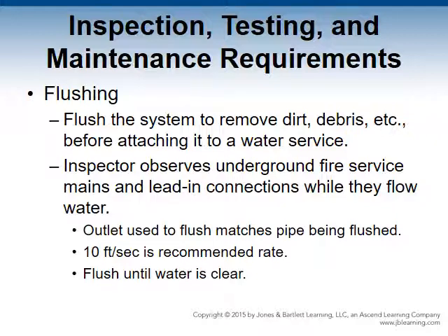Flushing. Before connecting the standpipe system to any water service, the supply piping must be flushed. This is going to remove dirt, stones, and other debris that could clog or damage the system or compromise its performance in any way. The inspector observes the underground fire service mains and leads-in while they flow water. It is a simple process. It is best if the outlets used to flush are the same size as the pipes being flushed.